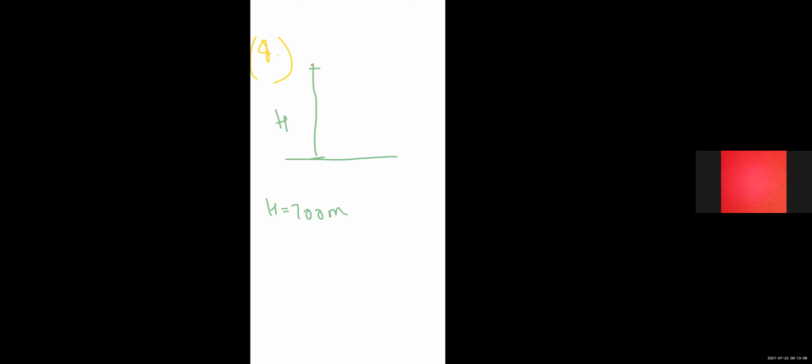Also, the radial distances of the top and bottom of the tower from the principal point are 112.5 mm and r dash equal to 82.4 mm. The bottom of the tower is at an elevation of 250 meters above the datum. So what is the actual height of the tower?